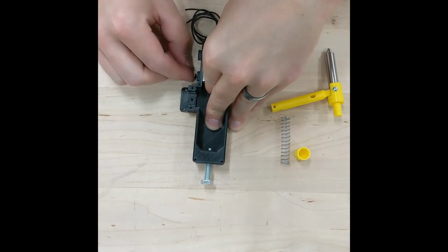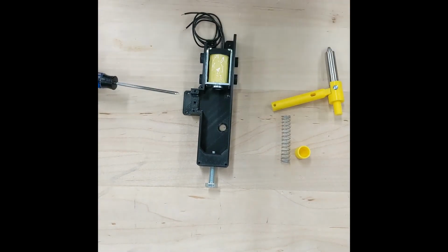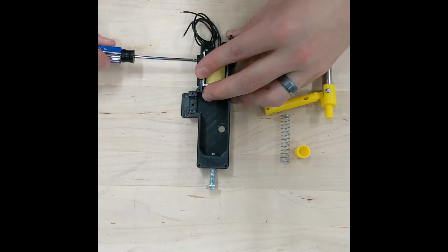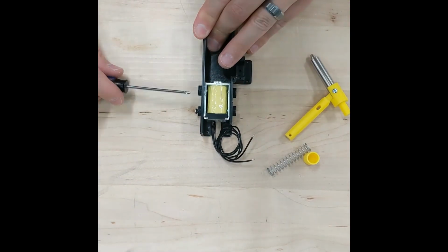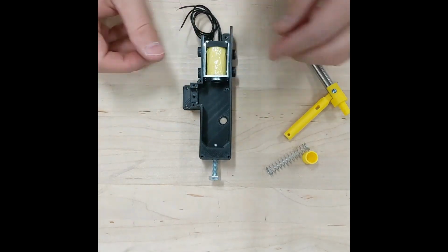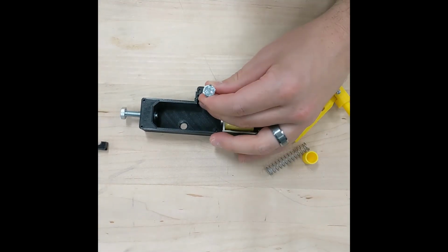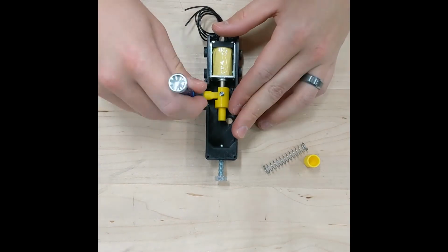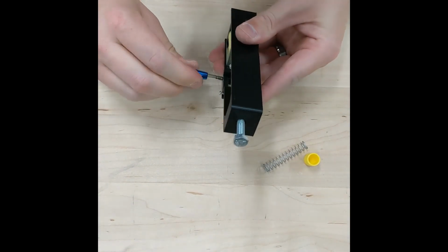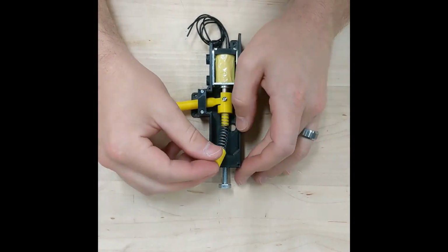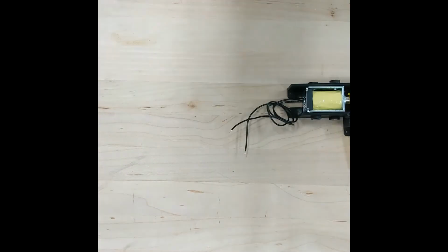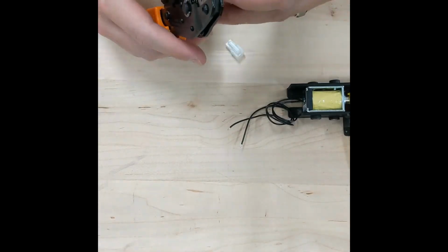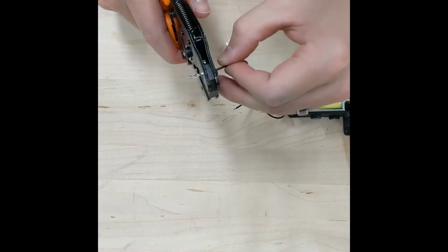The system was redesigned to utilize a pivoting arm with a fulcrum in the middle to change the direction of the force put on the locking mechanism. When the solenoid was powered, the pivot arm is pulled towards the solenoid, which in turn raises the other end of the arm that is connected to the locking mechanism. This releases the door from the lock and opens the locker. When power is removed from the solenoid, the pivot arm attached to the solenoid is released, moving the locking mechanism back in place to secure the locker when the door is shut.